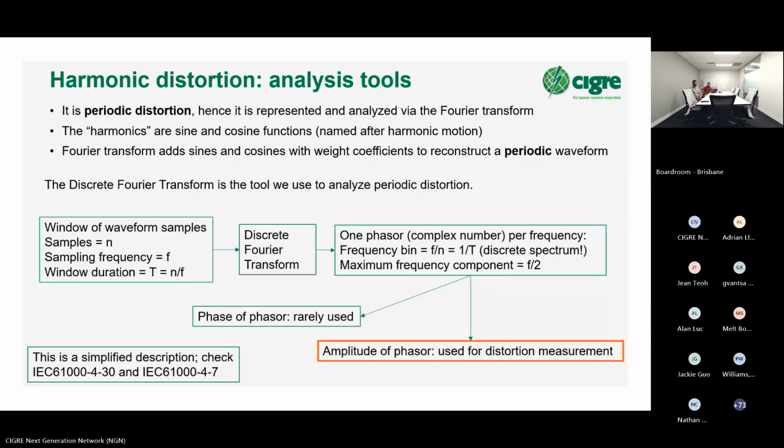The DFT doesn't lose any information. You can do the DFT and then do inverse DFT, you get the same signal. You don't lose any information. It's not like doing an MP3 file, that you do your recording, compress it in MP3, you can't decompress it and get the same one because it's a lossy compression. There is no loss, there is no change in information.